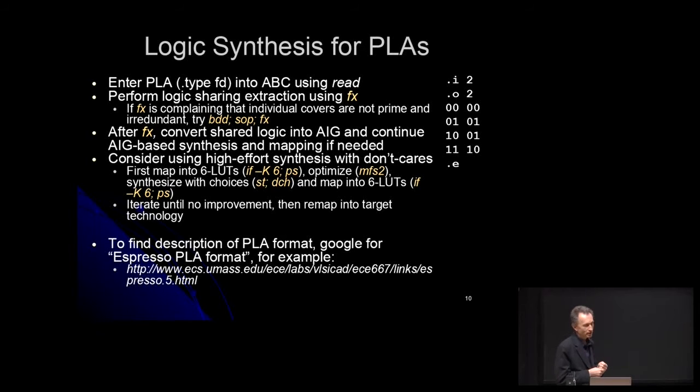So many designers or people who play with the logic synthesis tools will begin by specifying a PLA file. Here I just show a very simple PLA file to represent a half adder. A half adder has 2 inputs, 2 outputs, and so you can just list all input combinations and see what the output would be. So if you present your circuit in this format, you can read it into ABC,